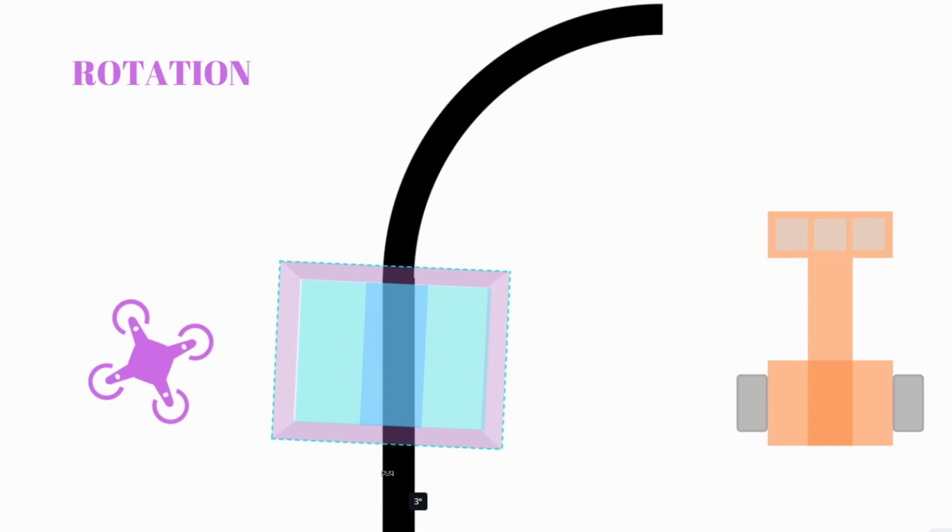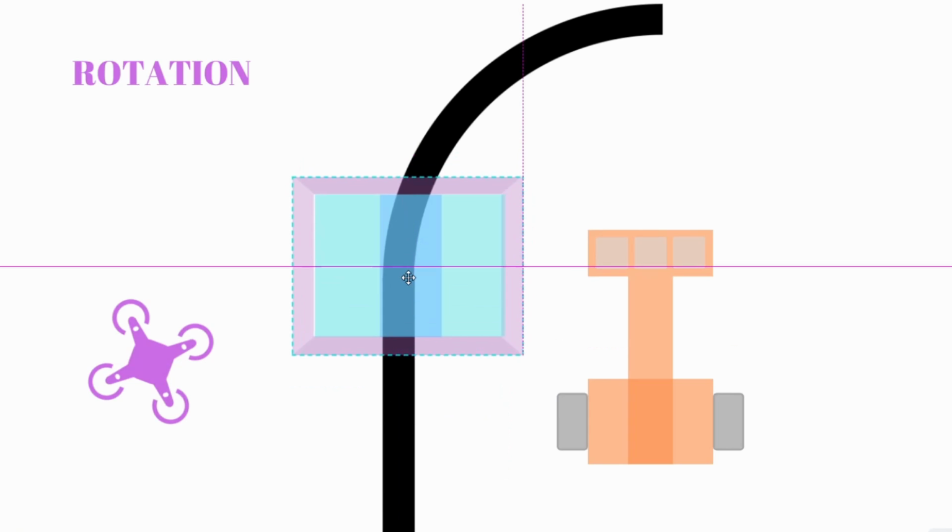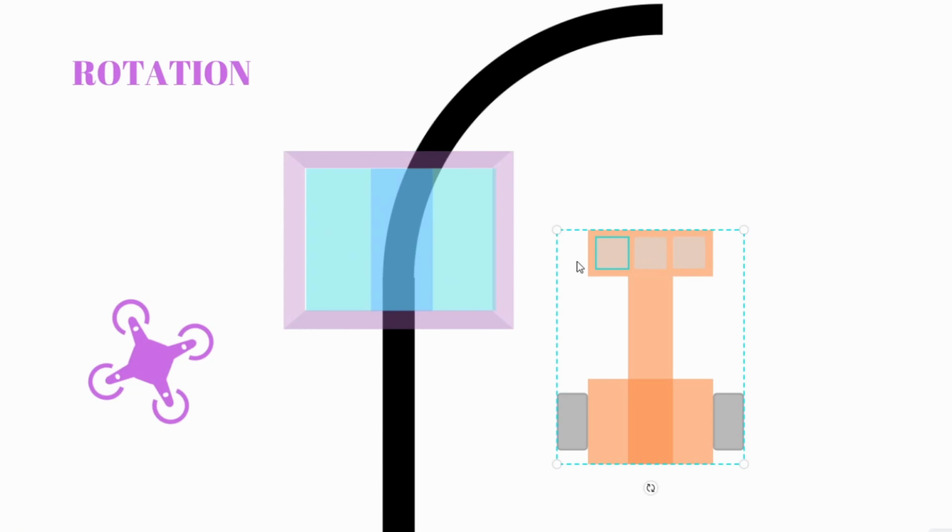So the idea is exactly the same as the line follower robot. All we are doing is we are converting our image to 3 different sensor zones. So right, middle, and left. Now because these are virtual zones, what we can do is we can split them into more regions as well. We can make them 5, we can make them 10. But the problem is, if we have more than 3, let's say we have 5, then we will have 2 to the power of 5 different combinations. So that is a lot of combinations to handle. So I would suggest to go with 3. And if you want to try it out, you can try with 5 as well.